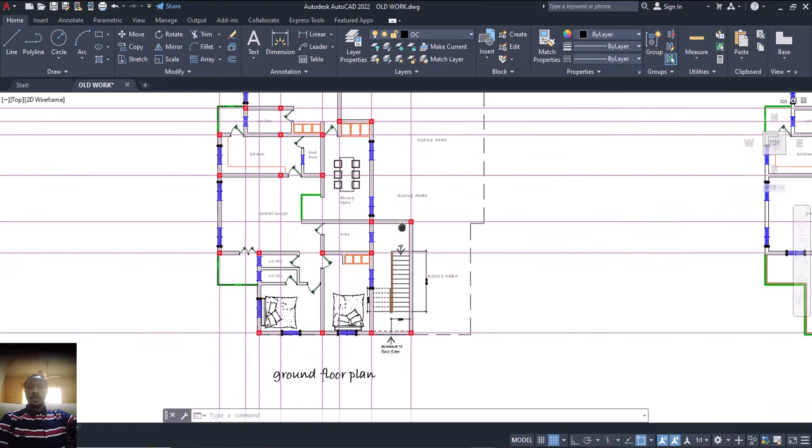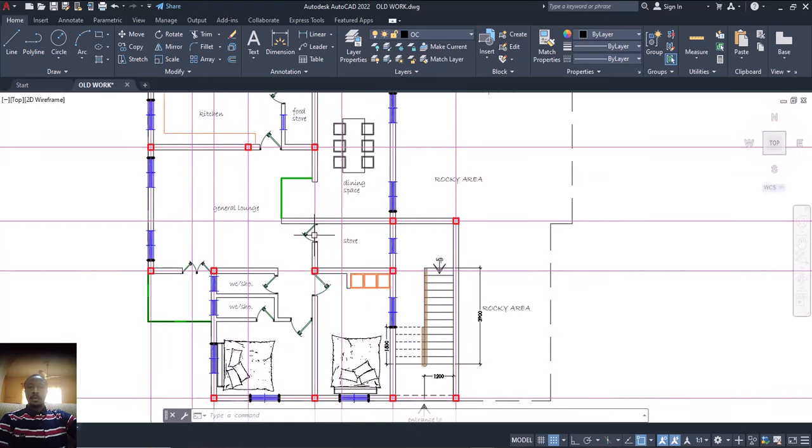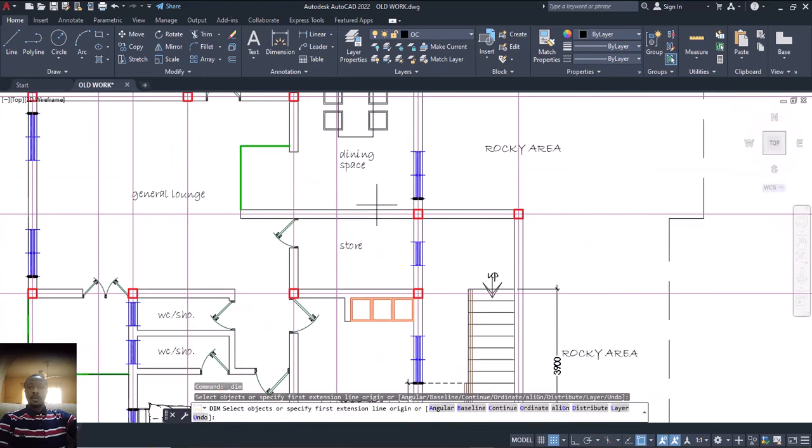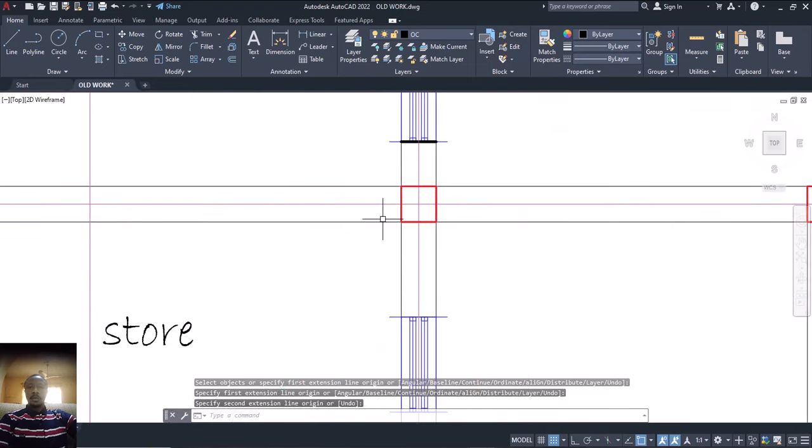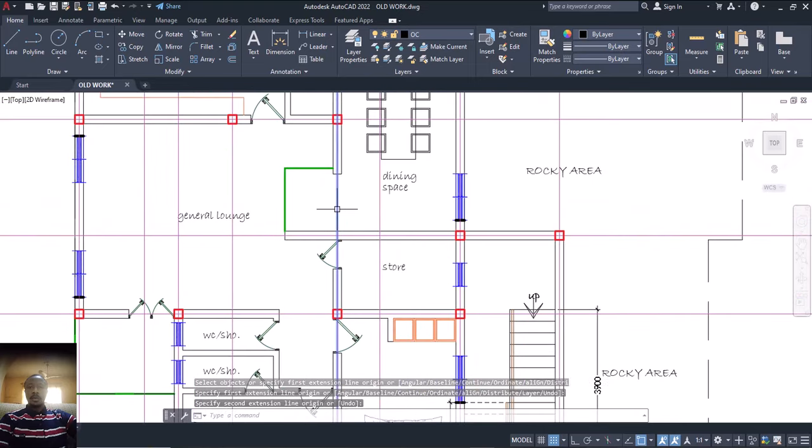Okay, so I haven't explained that. So let's now see. Based on this judgment, let's look at the length of this. From here to this place is 3 point something, which is okay, but this extension here now, understand? If I have this one here and this beam is coming to rest on this beam, then this will now become a cantilever. Is that okay? So on that ground, let me just do something like this. Let me have a column for this. Is that okay?